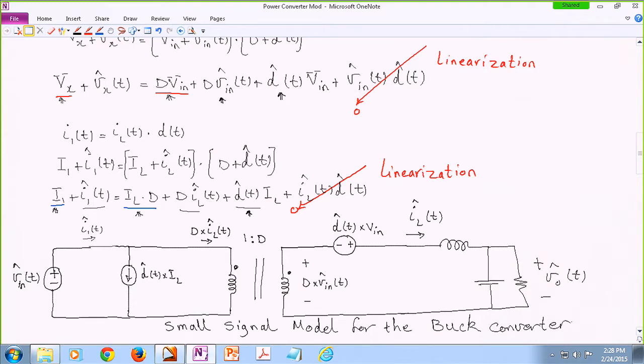Okay, so it is a time invariant model. In other words, independent of what time it is, none of the parameters or the structure of the system varies. We got rid of the time variancy when we represented the average model as opposed to the switching model, because switches are time dependent. Sometimes they are on, sometimes they are off. When we take the switches off and replace them with the average behavior of a switch, you are getting rid of the time dependency in the system.